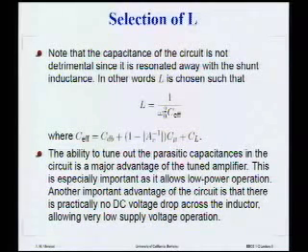There are other advantages of this circuit. Another advantage of the circuit is that there's no DC drop across the inductor, right? No matter how much current I put through that inductor, because it has a very small series resistance, there's practically no DC drop. In other words, let me compare two amplifiers here.